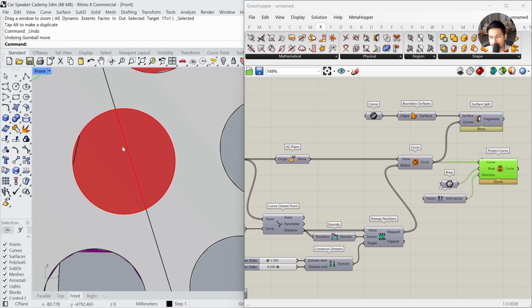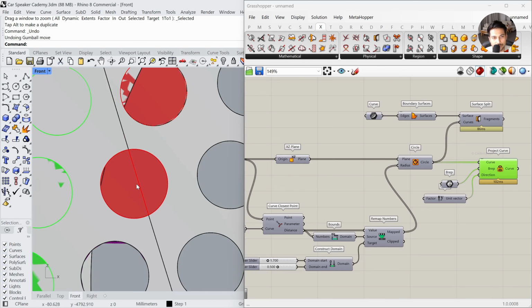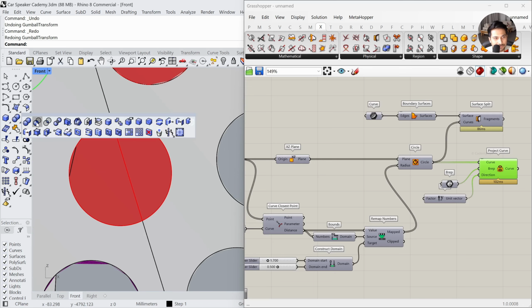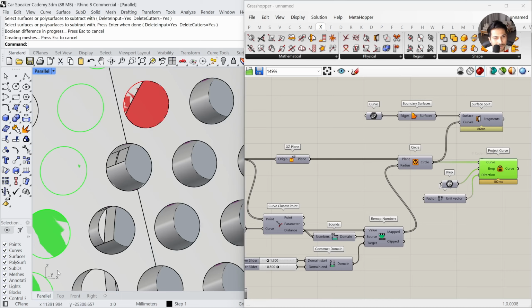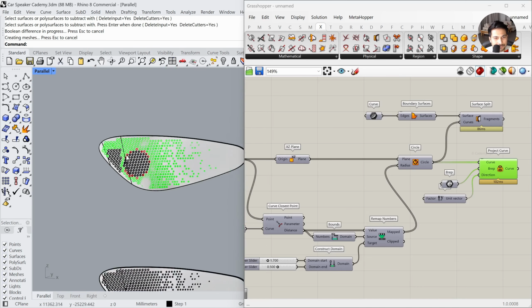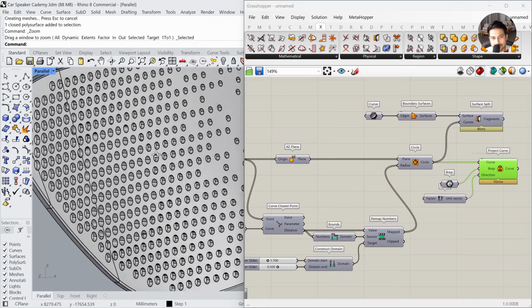Now again, this is a very microscopic change. In the overall scale, you won't even notice what I have done. Okay, so once we scale, let's rerun the Boolean difference, remove from here with that. And now you should see it work. Okay, so once you have run the command for all the edges, you should be seeing a final output that looks something like this.